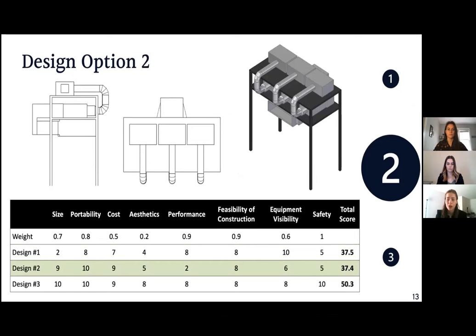It also could have performance suffer, as there's a lack of a straight line of ductwork into the inlet of the airflow control boxes, which was a recommendation based on the specification sheets of the airflow control boxes, that there be a minimum of 12 inches of straight ductwork into the inlet for optimum performance. So this could cause the performance to suffer.